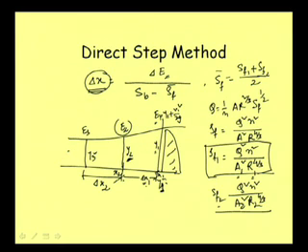That means this difference between E2 and E3 will be our delta E. Then we can calculate SF2 here, 2 means SF3 we can calculate, and that means just following the same procedure that we have adopted for computing from here to here, we can now, knowing this y2, compute this distance delta x2, which will correspond to another depth that we are considering from our side, y3. So this way we are calculating delta x2.